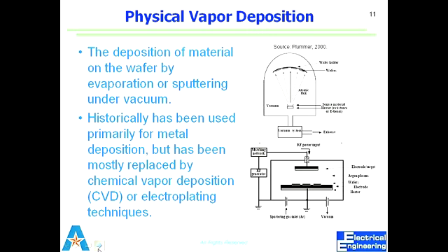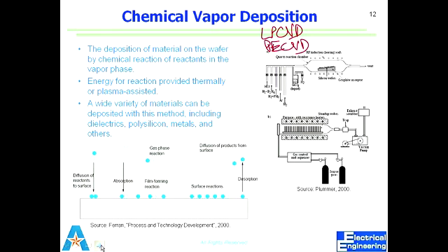There are a couple of different types of CVDs. One is called plasma enhanced CVD, which is this case. There is another which is called LPCVD, low pressure CVD. In low pressure CVD, we don't use plasma, but essentially it's again a chemical deposition process. We'll look at these later on. So in LPCVD, we supply a number of gases, maintain low pressure. The reaction results in some products which get deposited onto our wafers.